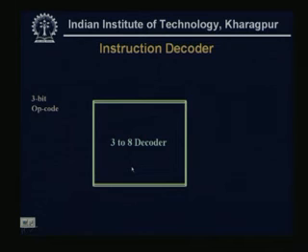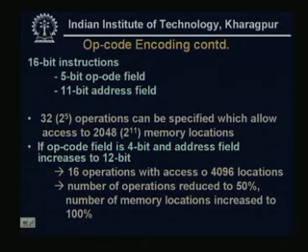Now, we want to design this, so we need hardware for this opcode field. In the hypothetical example we have shown, we have 8 instructions and we need a 3-bit opcode for that.